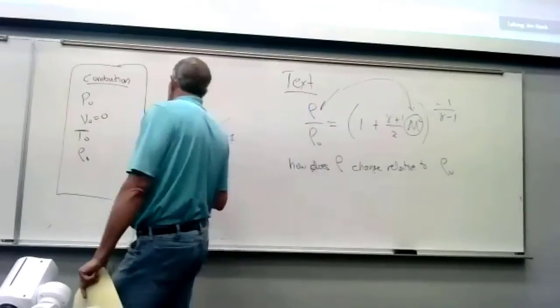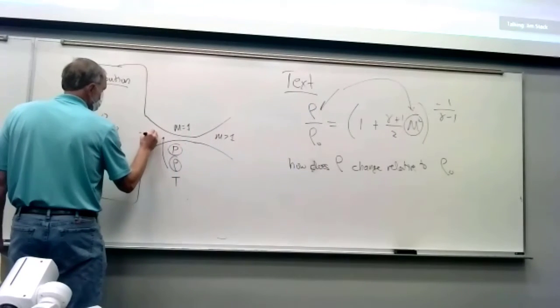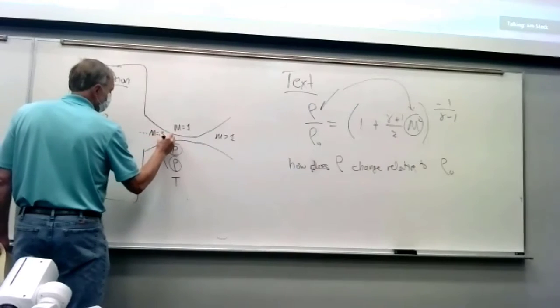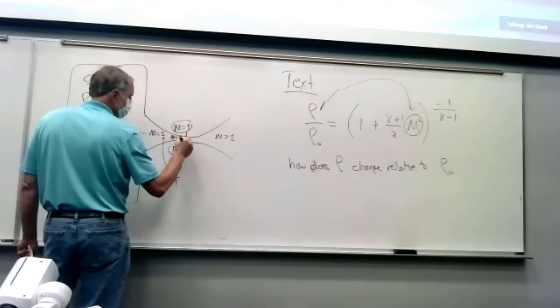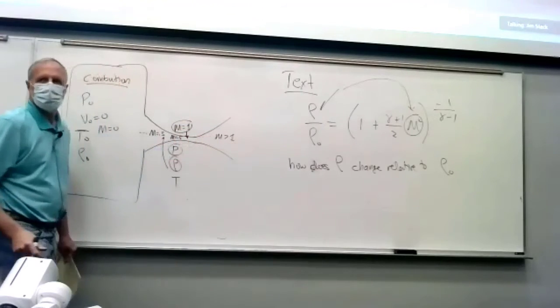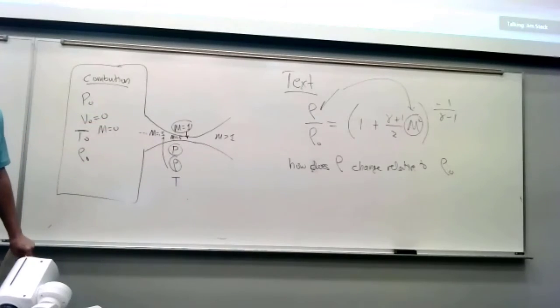As we're going through the nozzle, here obviously Mach number is 0. As you go through here, maybe you hit 0.3. You get further in here, you get 0.5. And then you get Mach 1 at the throat. And then you get Mach 2 as it goes out. So that tells us, as we're moving through this nozzle, how much the density changes.